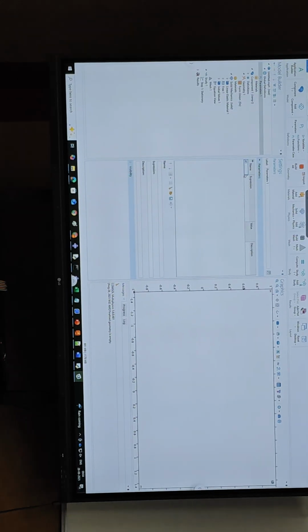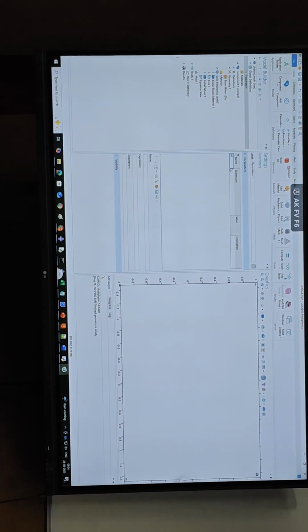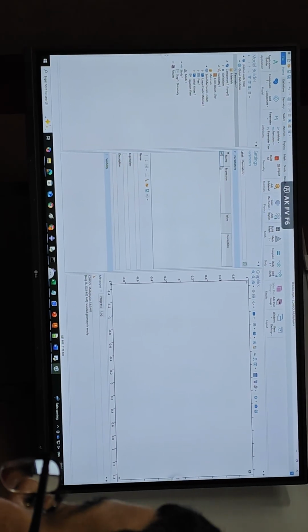So I'm doing one thing here. Because we're using 2D, we have an out of plane thickness which will be common to everything. Each cannot have different out of plane thicknesses. So in order to accommodate the area of cross section, I will be using the in plane dimension as the variable and keeping the out of plane constant, so that the out of plane is 1. The in plane thickness will be the area of cross section.